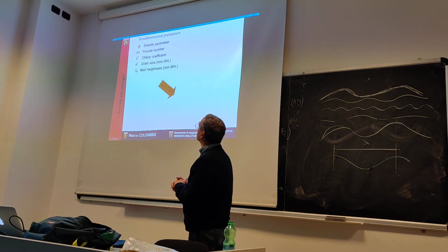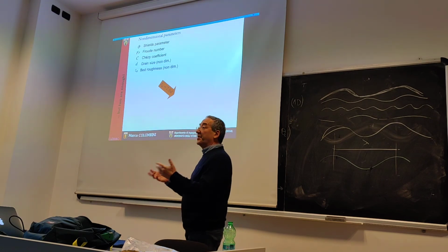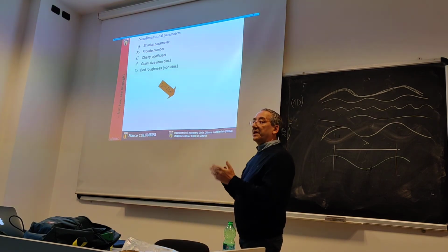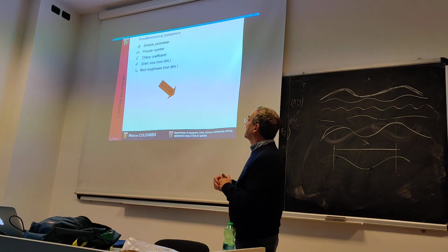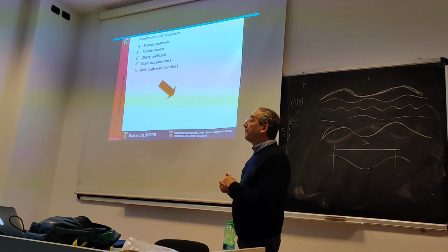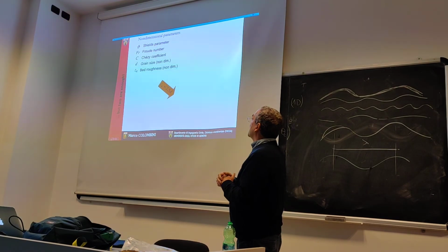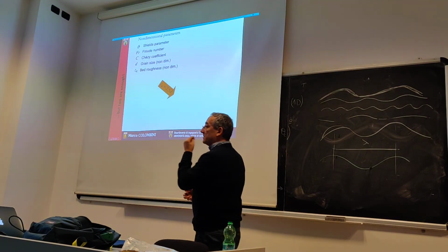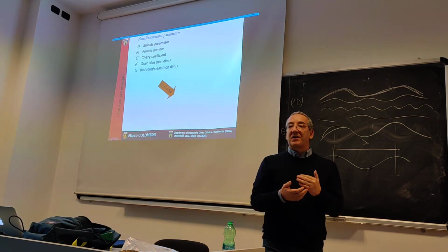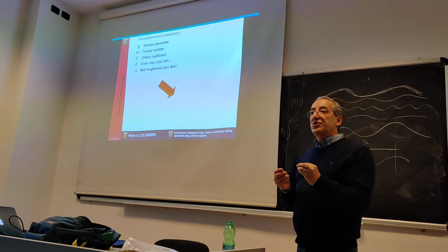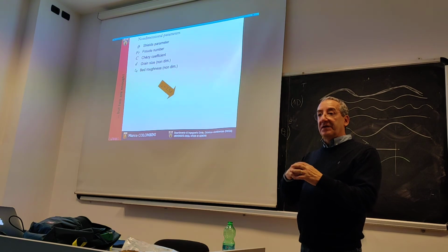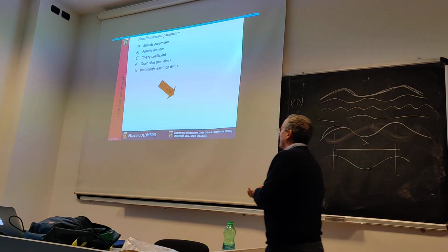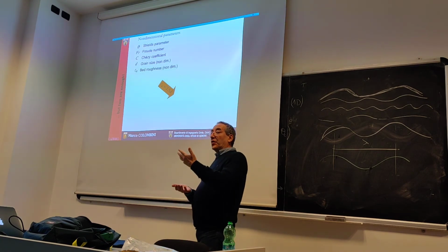For example, this is typically of the order of the flow depth with a proportionality constant that is about 2.5. So the roughness is a little larger, because, I remind you, the roughness measures the effect of the bed on the flow.